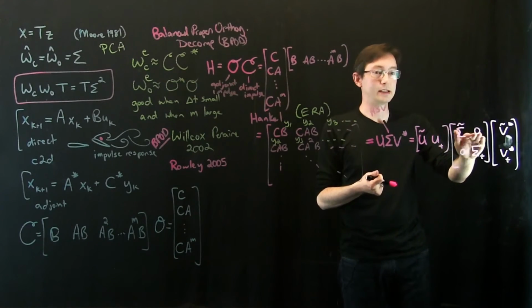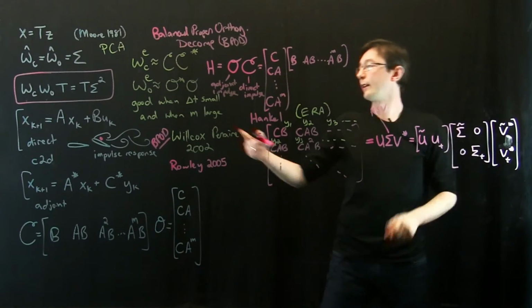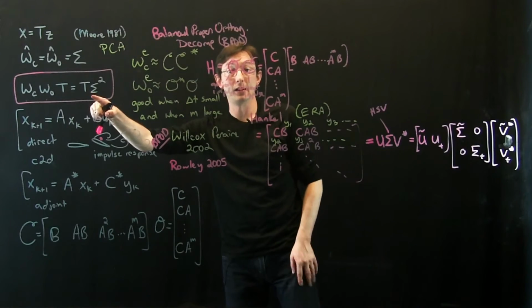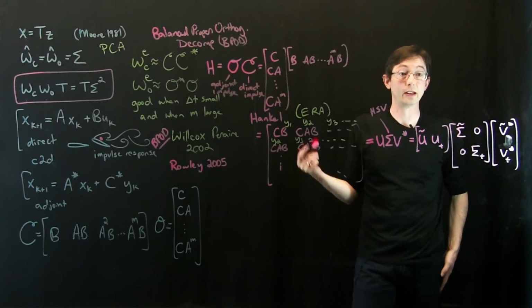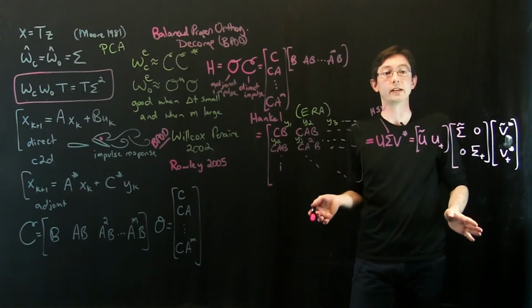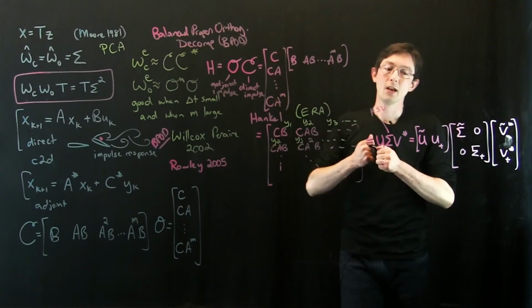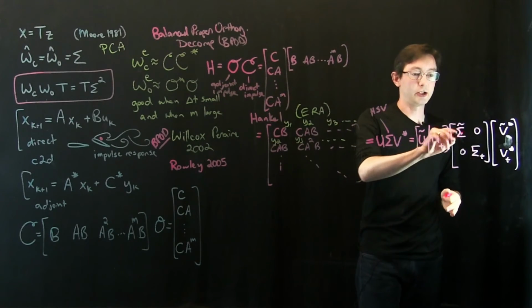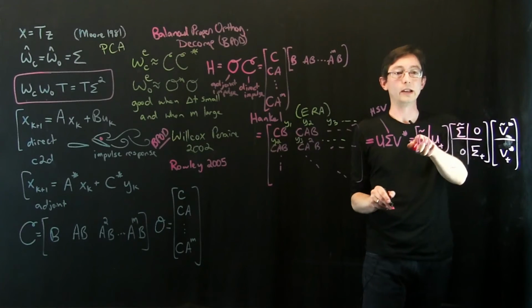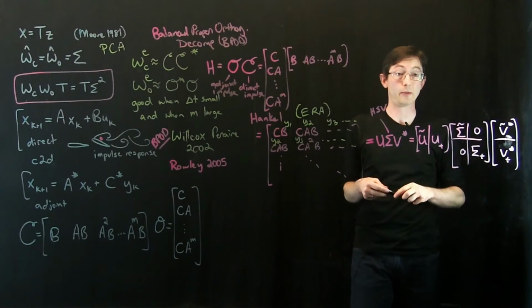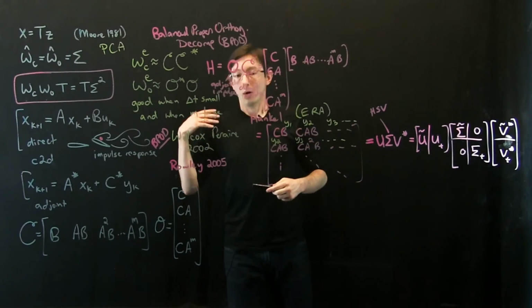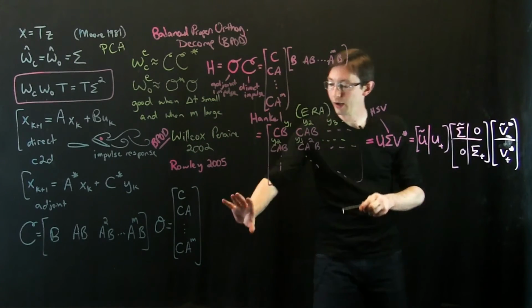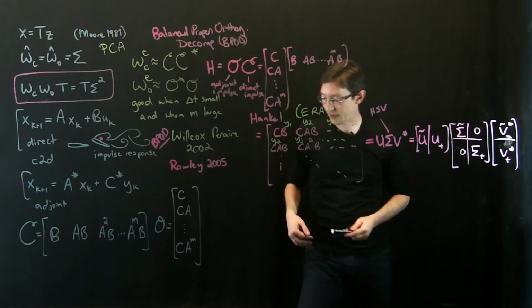And basically, the singular values here are very, very related to these diagonal elements of my balanced Gramian here. So these are the same Hankel singular values there. And this, again, then tells me how do I chop this system up to only keep the first R portion of this model. Okay. Whew, all right, a little bit longer. We're going to write down the last step now.